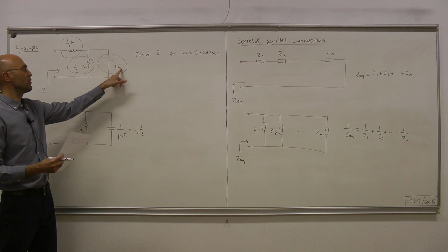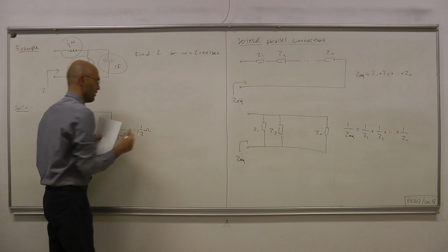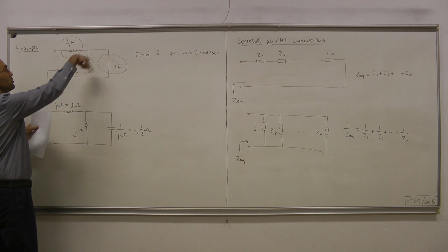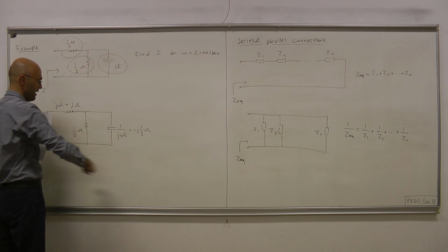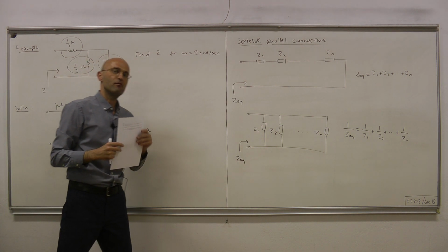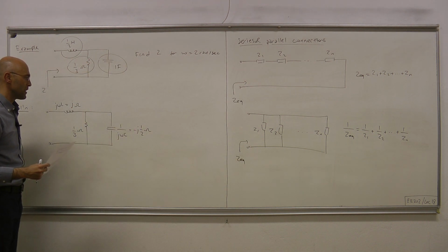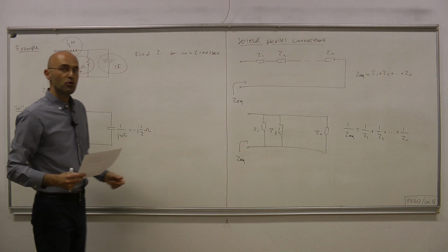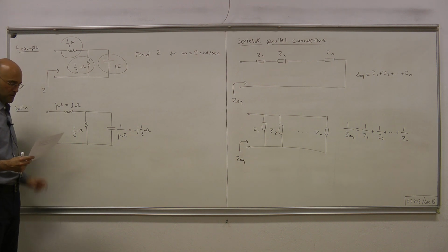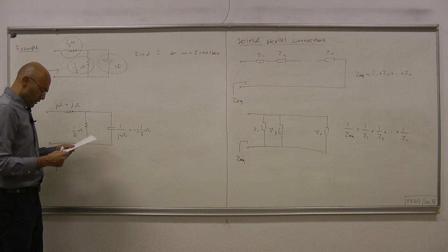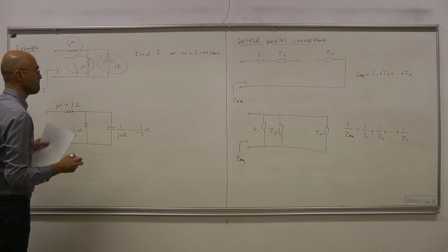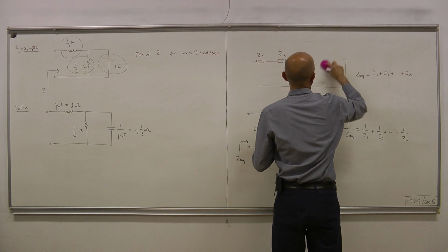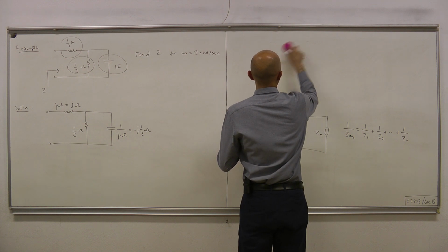The units, here we have farads, here we have ohms. Differential equation, algebraic equation. Note that we have 3 different units here, Henry, ohm, farads, but now everything is in ohms. So everything is represented by an algebraic equation, which allows us indirectly to talk about an equivalent impedance. So this is equivalent to the following.